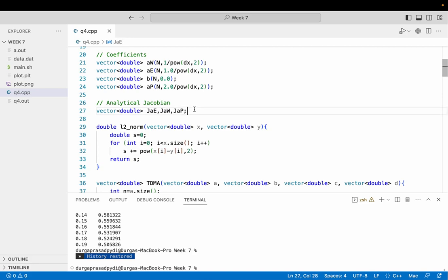So what I am doing here is we are explicitly specifying the Jacobian. So this is called an analytical Jacobian. If you are familiar with MATLAB, it does offer you functions to evaluate Jacobian numerically. Alternatively, you can also provide an analytical Jacobian. So for those of you who are familiar with MATLAB, you have an option to give Jacobian yourself. That will essentially reduce your computation cost.